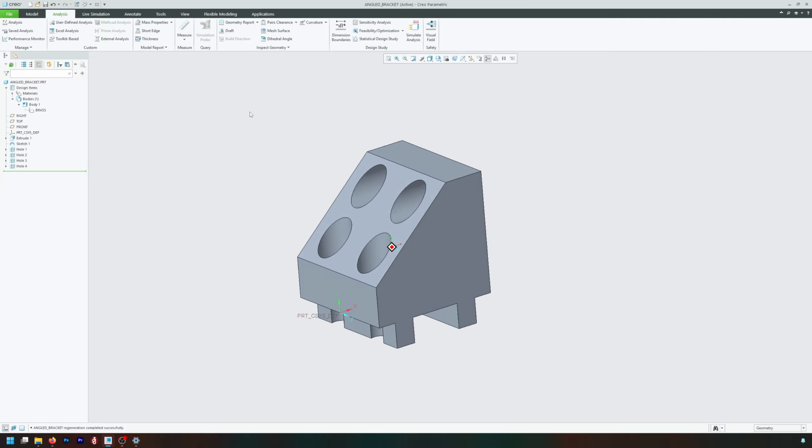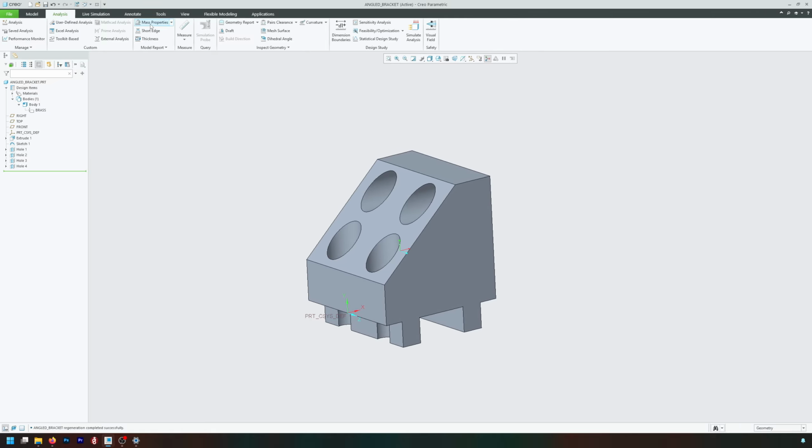So, in order to use the measuring tool, you're going to go over into Analysis, and you're going to hit Measure. Now, if you didn't turn that option on, this is what it looks like. Just these bare icons. I don't know about you, but this doesn't really tell me anything. However, if you turn on that config.pro setting, then it'll look like this. So all it really does, as the name implies, is it expands the dialog automatically for you, which is great because think about it. If you're taking 5,000 measurements, you're going to have to do this 5,000 times, right? That's not really what we're here for.